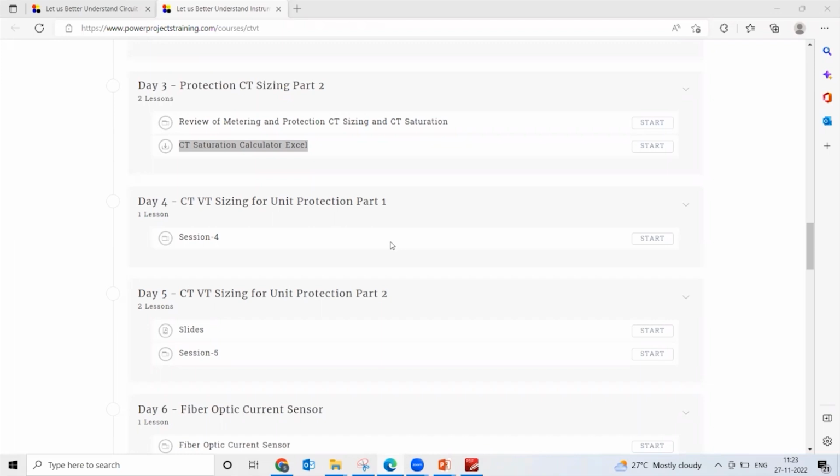So in directional overcurrent it is not that significant, whereas in a differential relay, if there is a phase error, it's reflected as a big mistake, right? So if I am missing, for example, a 30° error, then sine 30 is 1/2. I'm comparing a magnitude of 0 with 0.5, even during normal operation, and it will detect that as a fault and it will trip. So that's the reason why it is important. In directional overcurrent, it is not that significantly important.